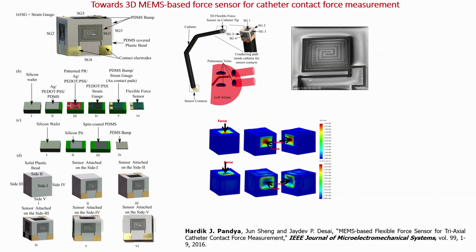Now, this is the simulation. Like I always say, no fabrication should be done until you perform a simulation. This is COMSOL Multiphysics; using COMSOL Multiphysics we have performed the simulation, and we applied force in different directions. Just a normal force, to understand the effect of applying force on the sensor, how much the sensor will bend. This is very important because if the sensor breaks, then it will not give a correct result. So, we need to understand the limit that a sensor can take the force, and that is why the simulation becomes very important.